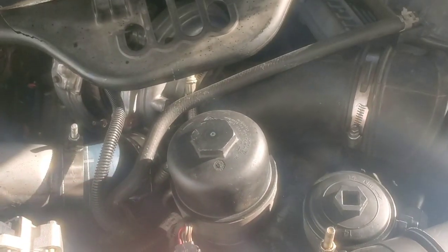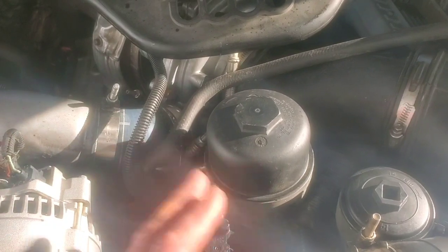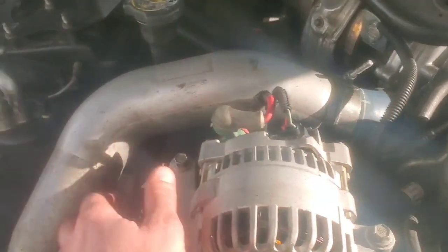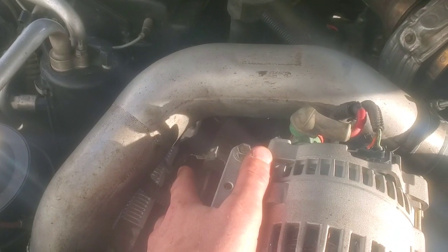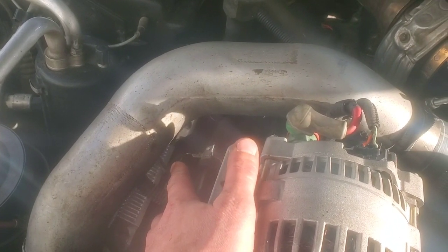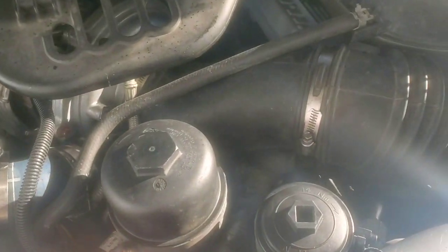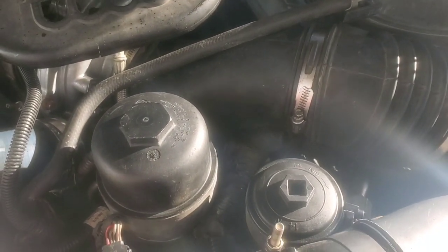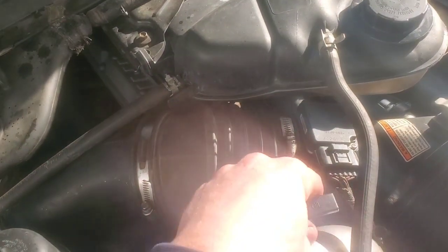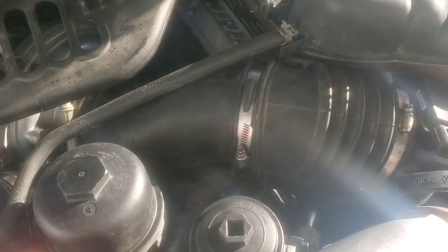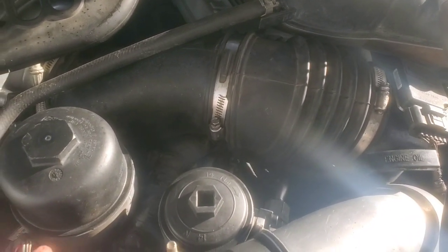So anyways, I don't really have much more information on this. Hopefully you might have seen something in this video. I wouldn't say guarantee, but when this thing would start with the ICP sensor unplugged, that's pretty much the circuit you're looking for. I happened to move this wiring harness a little bit too much and lost our symptom, and instead of spending time trying to find it, we're just going to go ahead and put a new harness in there.